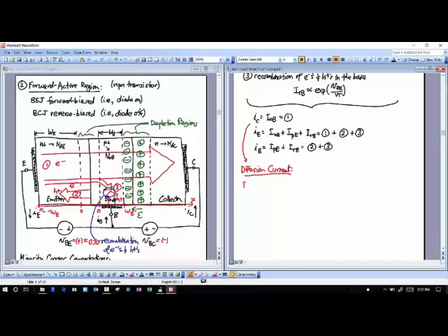This I_NB, which is the current of electrons in the base, is going to be equal to the cross-sectional area of the base times that diffusion current, and I put a negative sign in front of that because it's electrons, but times this J_N,B diffusion. Okay, remember that? And so now I'm going to expand this to be minus A times what that J_NB diffusion is.